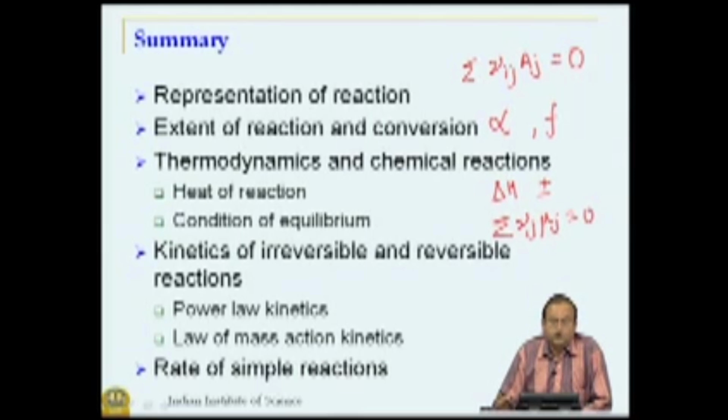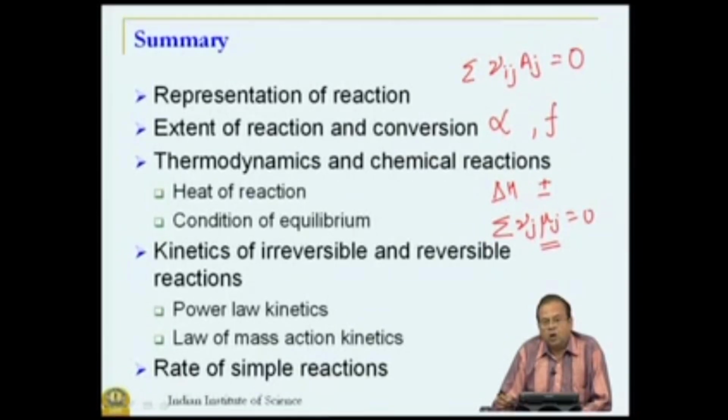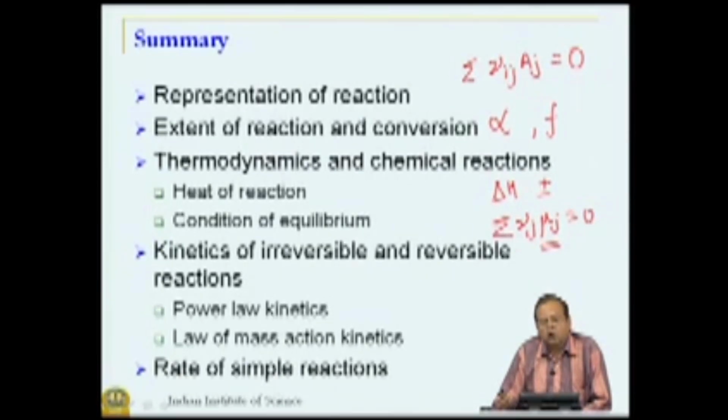Nu j as before are our stoichiometric coefficients, and mu j is nothing but our partial molar free energy, or the chemical potential. And we spent a little bit of time on how we define this chemical potential depending on whether the reaction is a gas phase reaction, a liquid phase reaction, a gas liquid reaction or gas solid reaction and so on. The condition of equilibrium remains the same, but how we define our chemical potential differs when we have different phases.